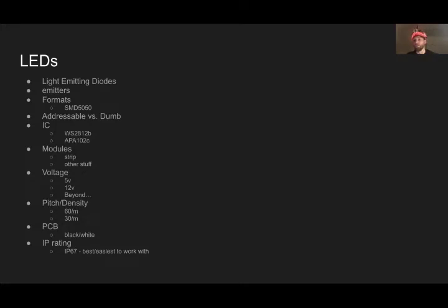It's quite hard to build an LED installation already, and it's even harder to build it twice, because there's typically some degradation of your materials, like people banging into them, the elements, etc. So things like dust and dirt can be just as bad for LEDs as water. And so the higher the IP rating, the better generally.